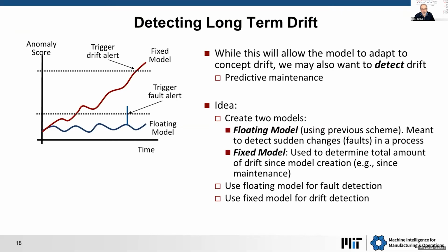But I might also maintain my earlier fixed model, not adding or compensating for known new good data points, and watch to see when I have drifted far enough away that that model has drifted away from current behavior. Now I'd say the model has drifted so much that you might want to go back and recalibrate, retune, or reset, perhaps do periodic maintenance on that particular tool.